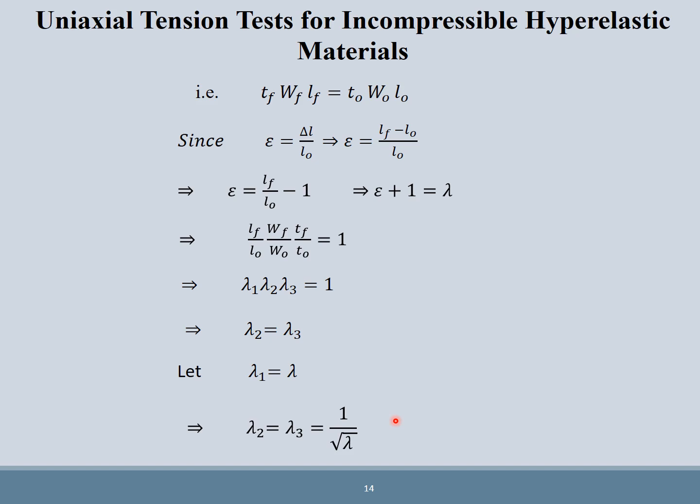So if we are given the axial strain or axial stretch, that is the stretch in the lengthwise direction, and let's say the value is 2, we can directly use that as lambda 1. But if you want to calculate the lateral, how are we going to calculate it? We just put 2 in this formula and simplify, so we get the lateral stretches.